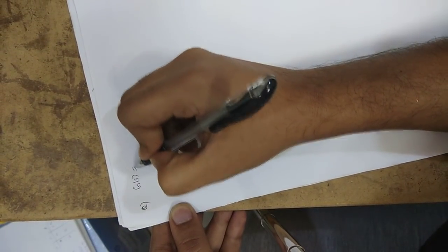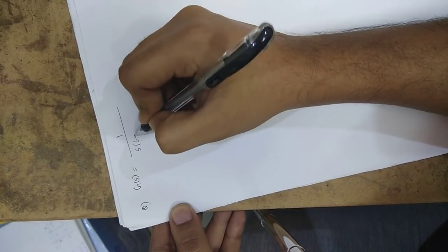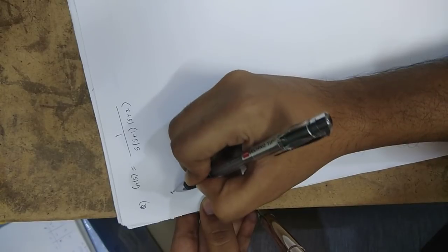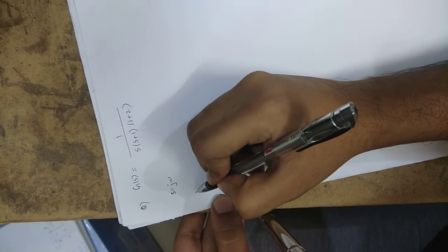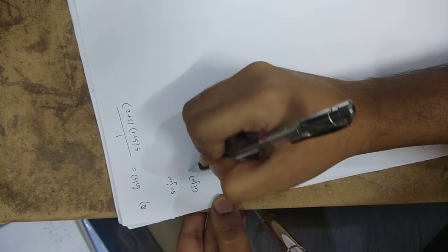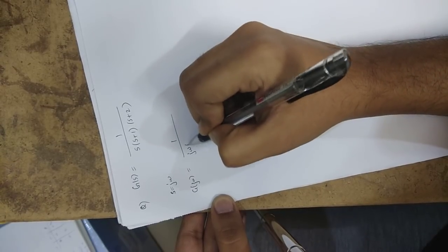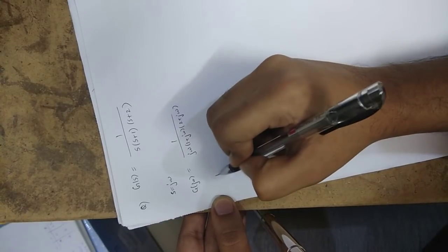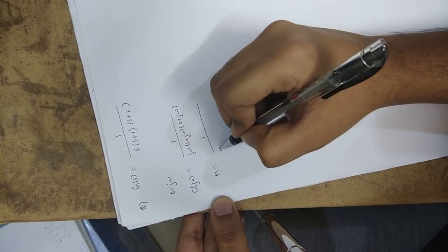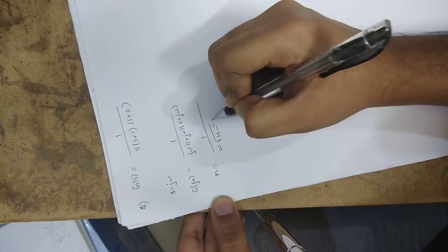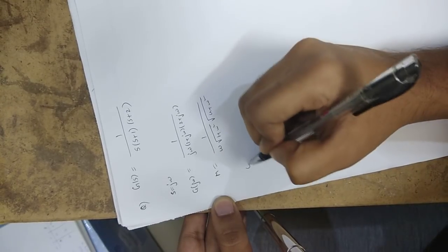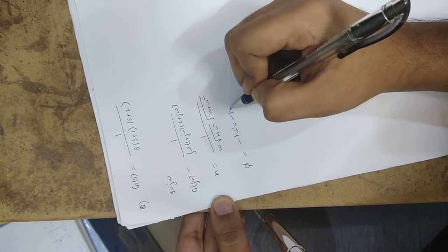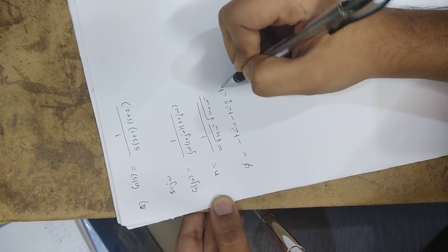G of s is 1 by s into (s plus 1)(s plus 2). Same, substitute s equals j omega. Find the magnitude. G of j omega is equal to 1 by j omega (1 plus j omega)(2 plus j omega). So what will be the magnitude? 1 by omega square root of (1 plus omega square)(4 plus omega square). What will be the phase? Minus tan inverse omega, minus tan inverse omega by 2, minus tan inverse